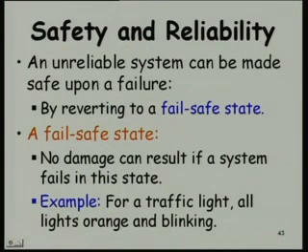There is an example here. A traffic light controller at a road intersection, even if it fails, leaves the lights orange and blinking. This is a safe state here. Suppose it failed with the lights all green at the intersection, it will become unsafe, accidents, people will rush in. If it fails in all red, that will be unsafe also, isn't it?